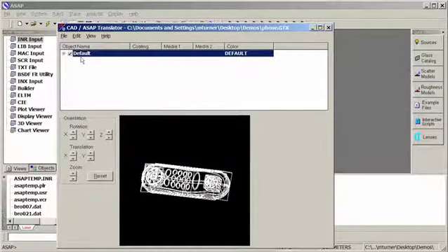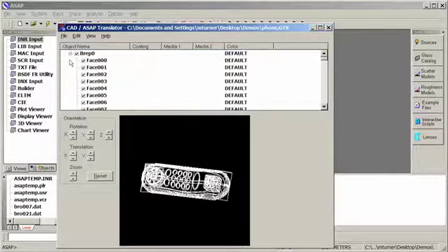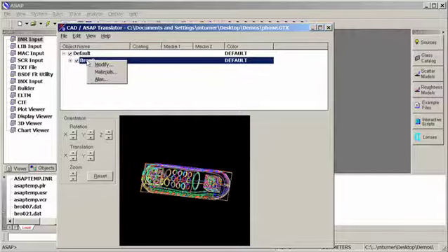So what I'm going to do now is within this file I can also choose to apply properties and or coatings to the component, and we can look at the drop down tree, and you'll notice it's made up of several surfaces that came over from SolidWorks. And up here you'll see the titles Coating, Media, and Color. And I can, within this translator, choose now to either on an individual face basis or to the object as a whole apply particular properties. And let me close this down. And by clicking the right mouse button, I have the option to add to my materials database, change the names, or in this case I'm simply going to modify the optical properties.